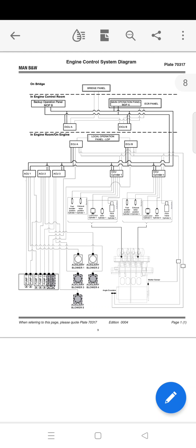Typically, MOP A is placed in a console opposite to the maneuvering handle and MOP B on a desk. The two MOPs are operationally fully redundant. Now, MOP A. This MOP type has no ordinary keyboard or mouse, though both may optionally be equipped. A trackball typically replaces the mouse. A keyboard is essentially not required during normal engine operation, and a virtual keyboard is displayed in case textual input like a password is needed.